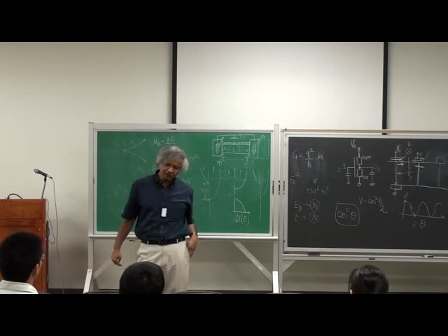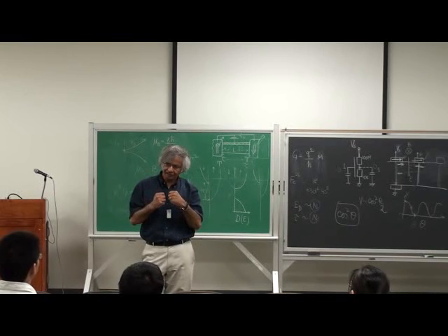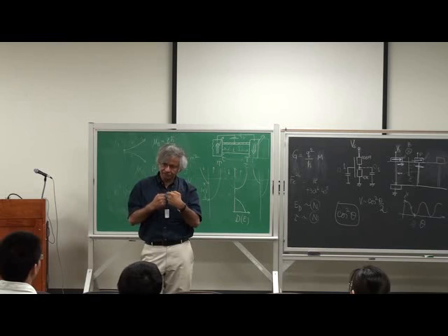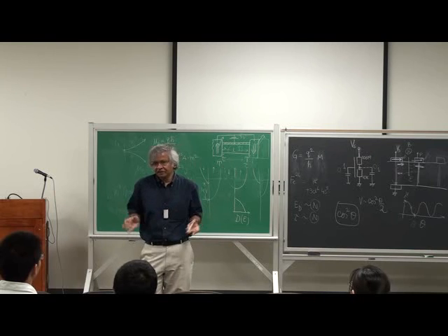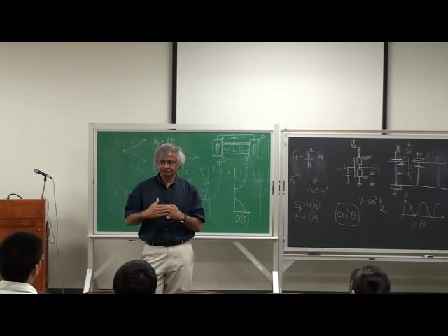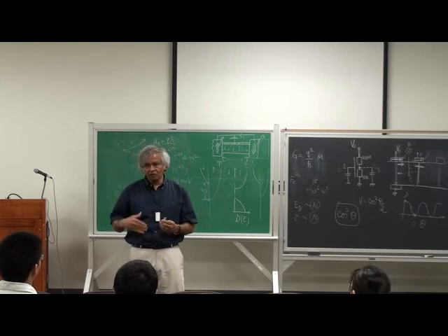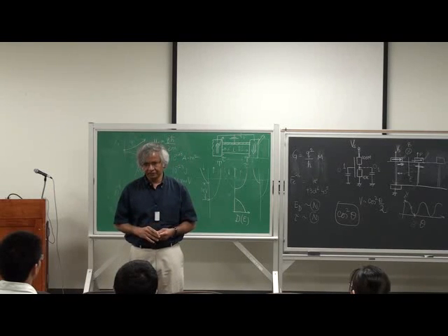With spintronic contacts, they are also out of equilibrium in a spin sense. So you'd say as if the two spins have two different chemical potentials, two different quasi-Fermi levels. So it's out of equilibrium. Whereas in ordinary devices, usually both spins are in equilibrium. Coherence time would determine how much out of equilibrium you can get.